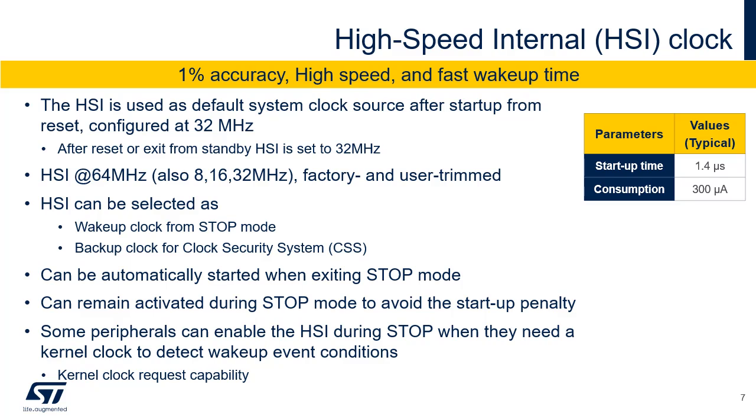The HSI can remain powered when the system goes to stop mode in order to speed up the wake-up time. Certain peripherals, such as the I2Cs and UART or LPUART, can request the activation of the HSI in system stop mode in order to generate wake-up events. The HSI is enabled by the peripheral only for the wake-up sequence detection and remains disabled outside of this wake-up